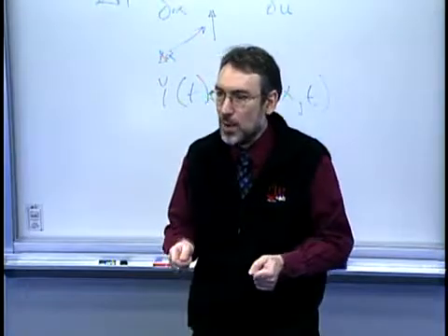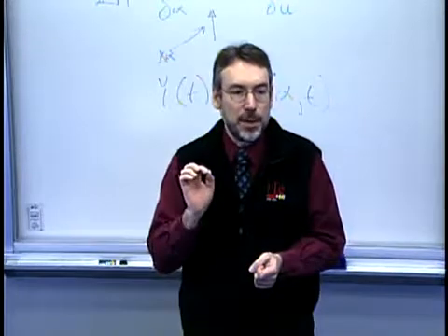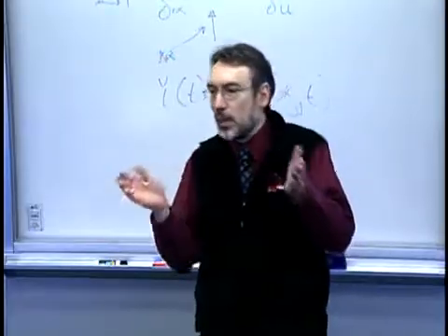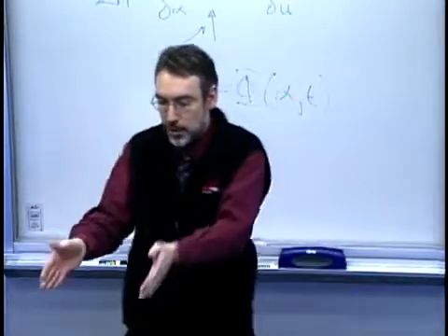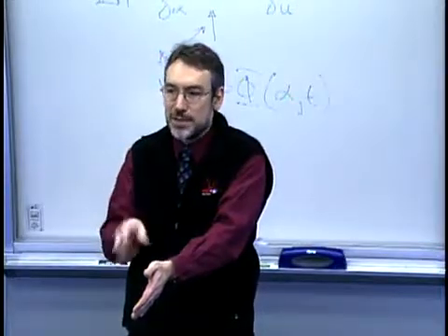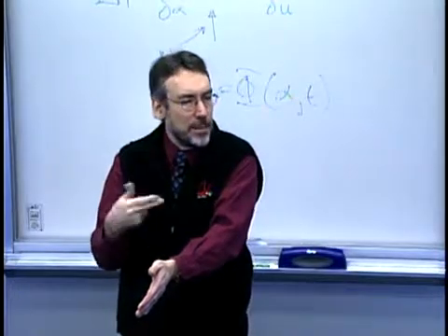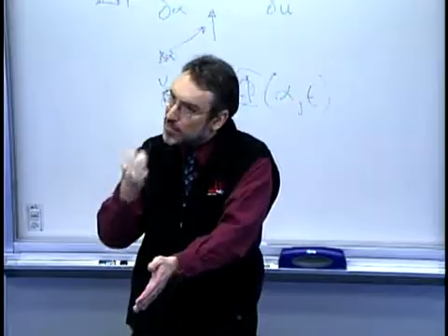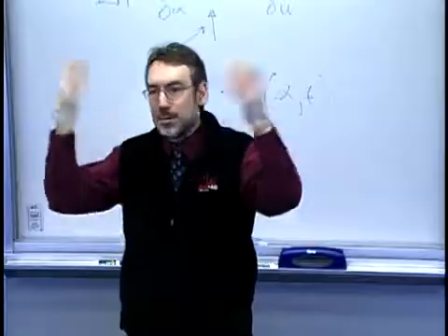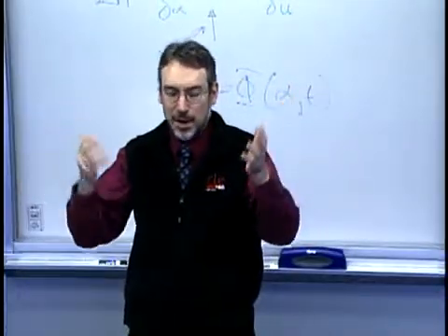So for example, there's a reproducibility and there's a repeatability component to typical gauge studies. One component, just real quickly, would be I've loaded the part on the measurement apparatus and then I just fire whatever the measurement sequence is multiple times. You can think of that as a pure repeatability. Somehow kind of the physical, maybe it's an optical measurement. There's a scatter from extraneous light sources nearby off of that.